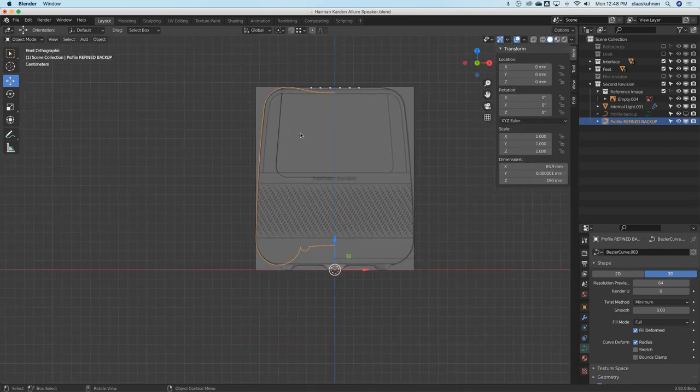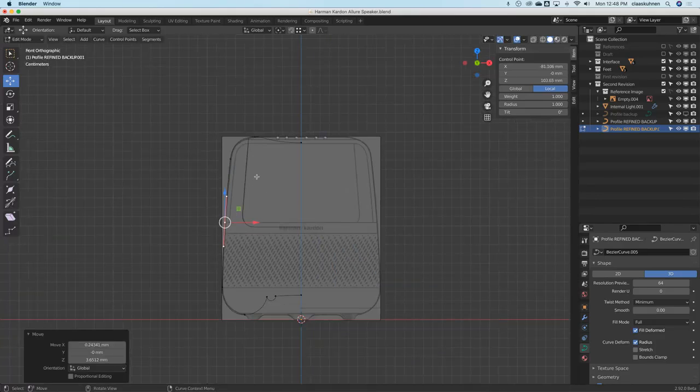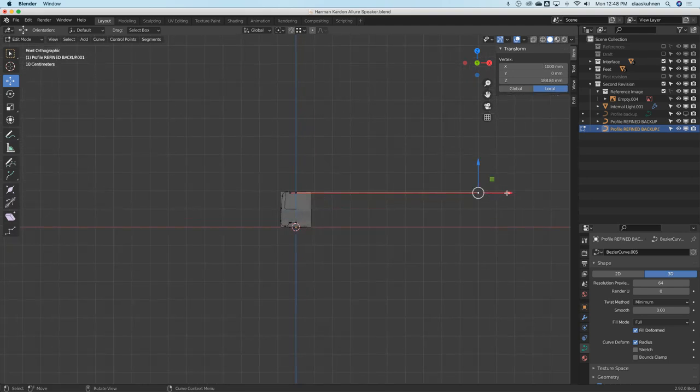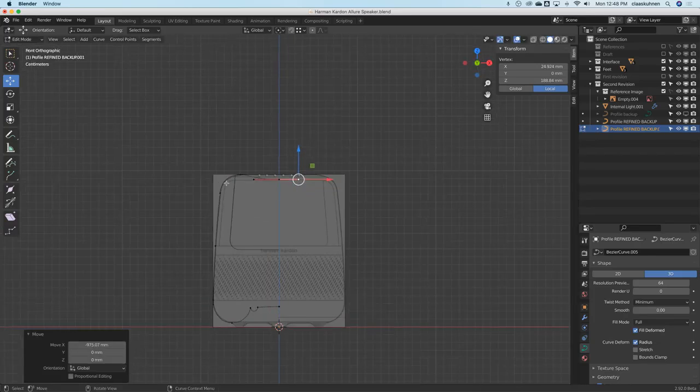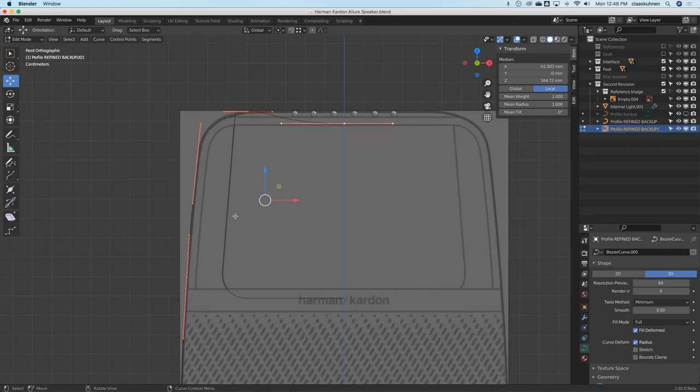Okay, good. So with this, again, Shift D and escape in object mode. Go to edit mode, and then this one we can slide up and then select. Whoa, how big is this one? I must have scaled it by accident. Select all this. Yeah. And now we say P and separate. And there you see that the copy we separated fully follows the original flow. How cool is that, no?